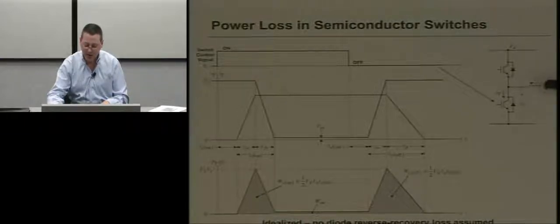And the characteristic here is that during the short switching interval, the inductor behaves like a current source. So when you're switching, I know Ned's probably explained the concept that you have kind of a voltage port on this side, and you have a current port on this side. So you're switching voltage here, driving current in this load. And the key thing to remember is that during that switching interval, especially in what we call hard switching, there's no way to get the traditional resistive kind of behavior.